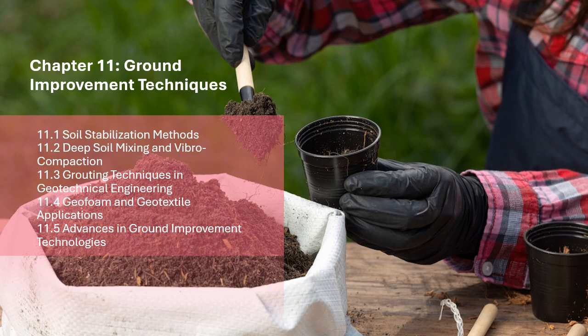The vibroflot is raised in stages while continuing to vibrate the soil, allowing for incremental densification at different levels. In some cases, the process is combined with the injection of water, air, or grout to further improve the soil's characteristics.